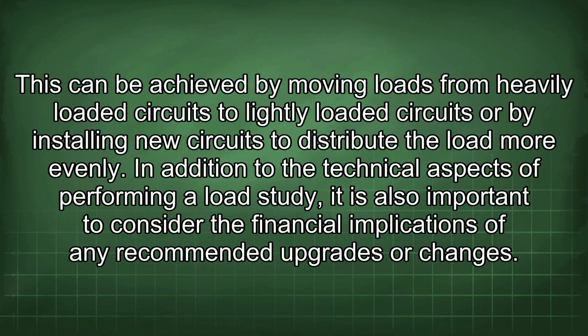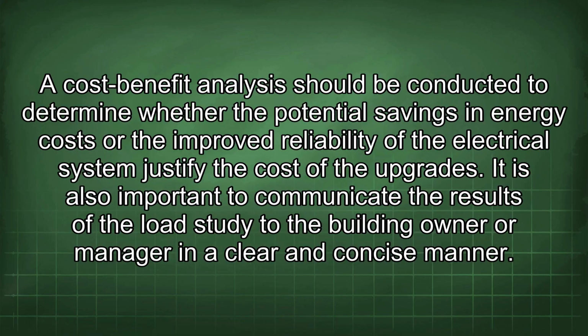This can be achieved by moving loads from heavily loaded circuits to lightly loaded circuits or by installing new circuits to distribute the load more evenly. In addition to the technical aspects of performing a load study, it is also important to consider the financial implications of any recommended upgrades or changes. A cost-benefit analysis should be conducted to determine whether the potential savings in energy costs or the improved reliability of the electrical system justify the cost of the upgrades.